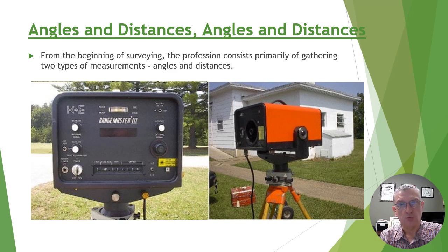Surveyors just needed to know that. They weren't always looking for a reason to point blame at the other surveyor, but they needed to know why that 5-foot difference was there. Was it that this had been measured sloppily? Was there a 5-foot bust in the traverse, and this is where it actually wound up at? Did Jim transpose some numbers? Did he get 97 and 79 backwards on something? The ability to go back in the field notes and explain the survey was paramount. That's what I want to stress.